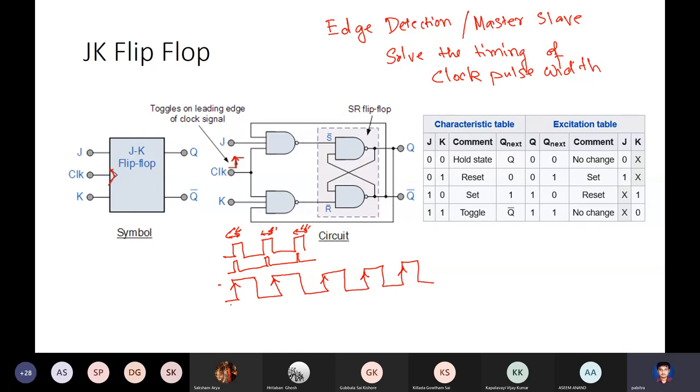Okay, so the latch can change, will consider the input, whatever is the value of this input in this snapshot of time. And the output also will change only at these events. What is this event? Up edge event, sometimes called a leading edge event. Only at this leading edge event. What is the event? Event is clock going up. Only that moment of time.